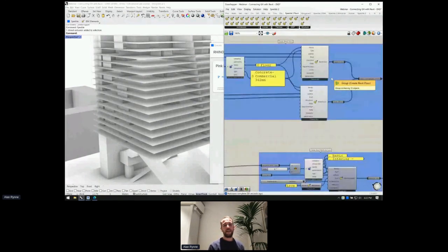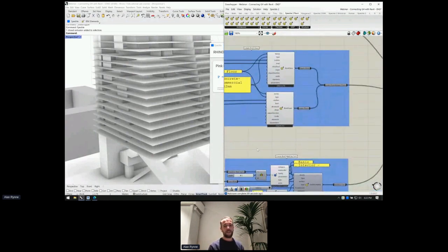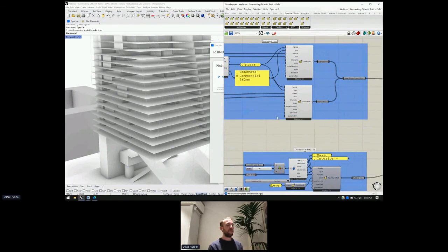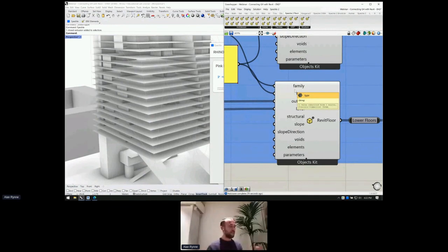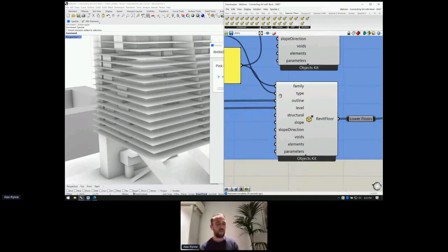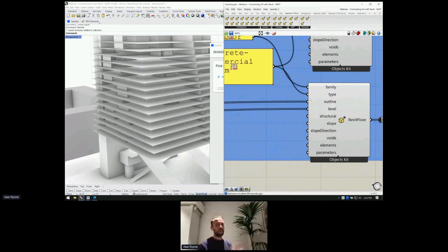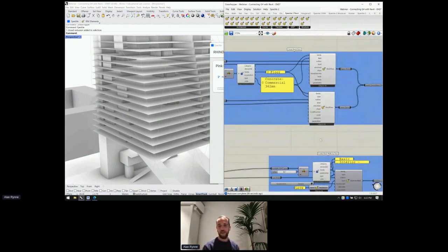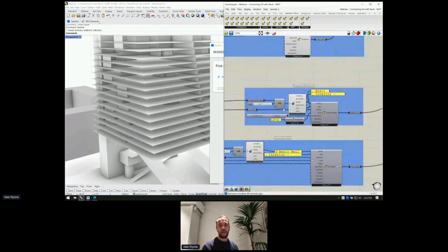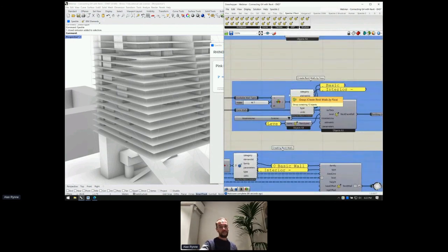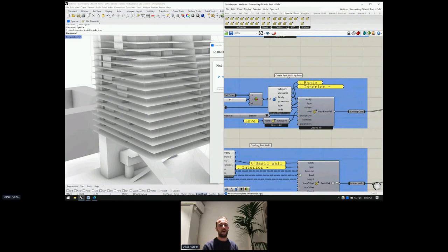So that was basically generating generic elements in Revit. Most of this applies to everything else. Any other object that appears here basically works in exactly the same way. The main trick is the family and type thing that is usually difficult to extract, and it's why we provide a way to extract all of those types in a specific kind of filter for you to use down the line.